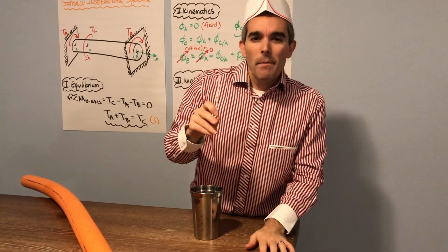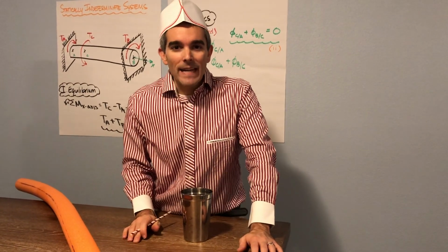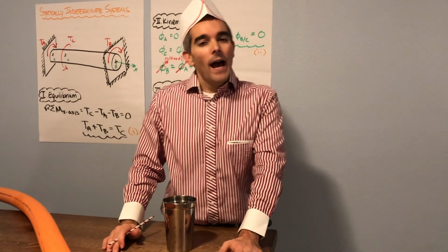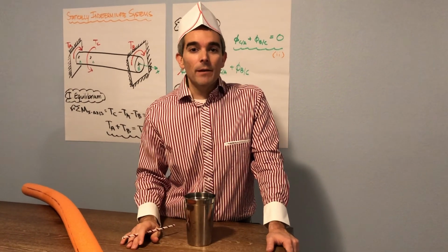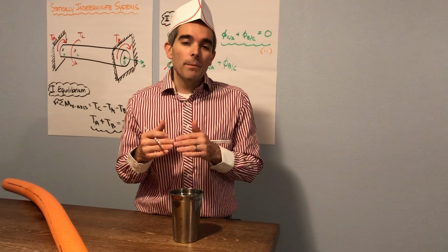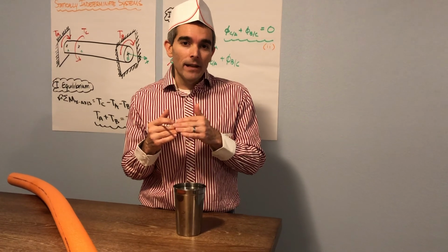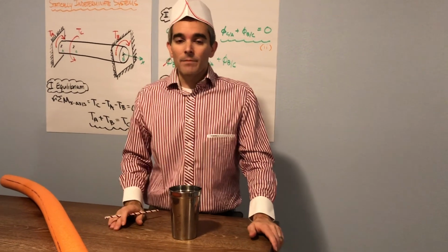Not quite failing. But I did want to point out I've covered one type of statically indeterminate problem, just like we did with one-dimensional axial forces, where we saw we could have a composite system where we have 2 materials that are bonded together and displacing all at once. We can have that for torsion systems too.